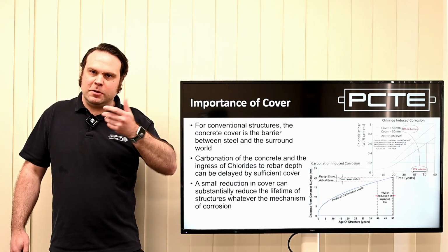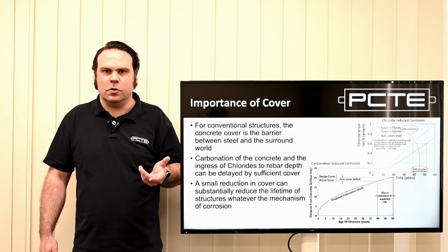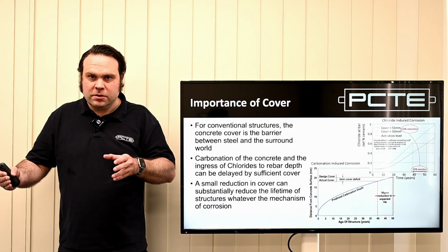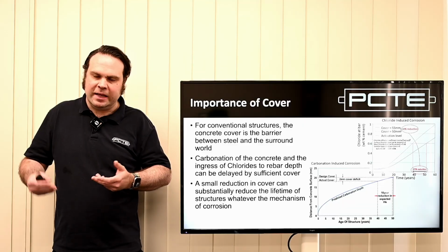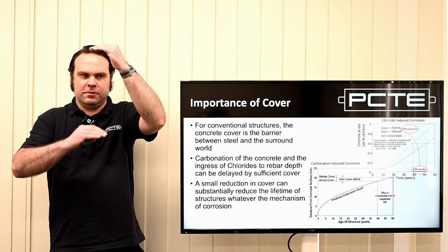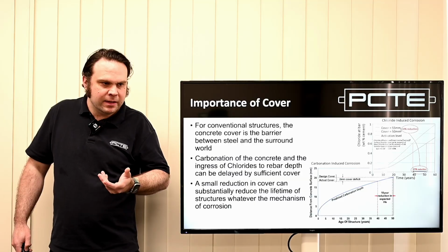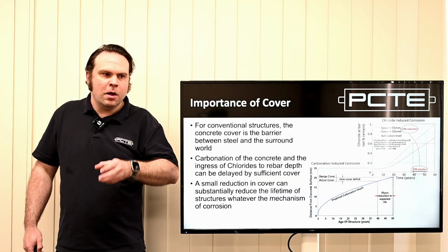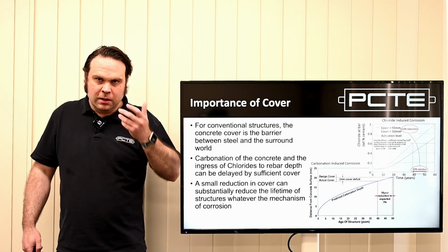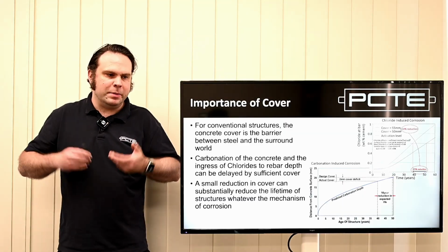What you'll find is that if we're talking about chloride-induced corrosion or damage to the structure, corrosion caused by carbonation, all of those, the first and best protection is solid, uncracked, undamaged concrete with sufficient depth above the reinforcing steel to give the expected design life. So when a durability designer does his best to plan out what that structure's life will be, that's where input of things like the cover will be involved. So with the cover meter, in addition to checking before the concrete is cast, we'll be able to check after.